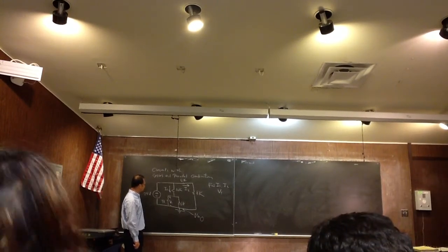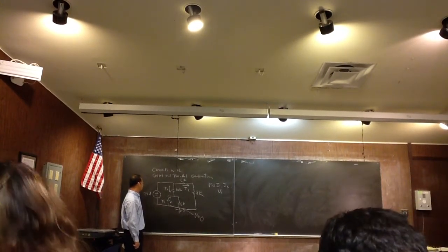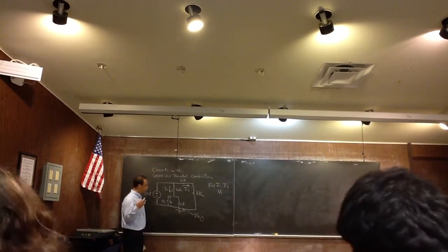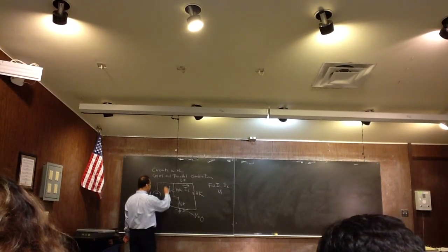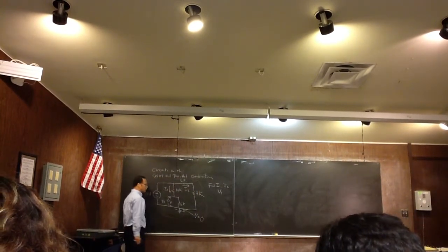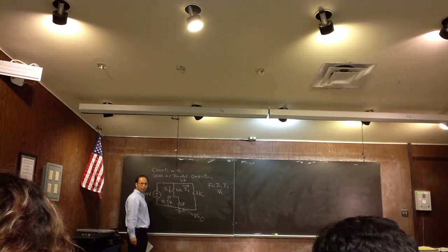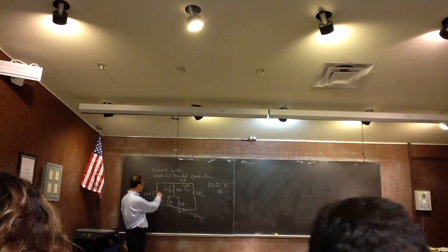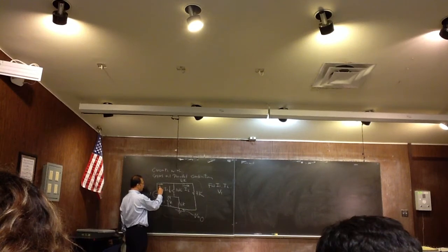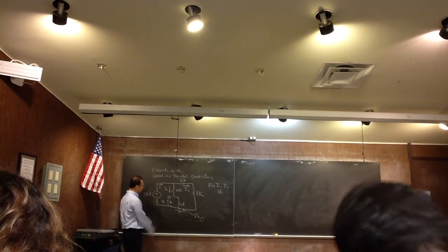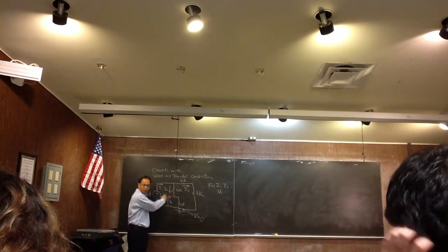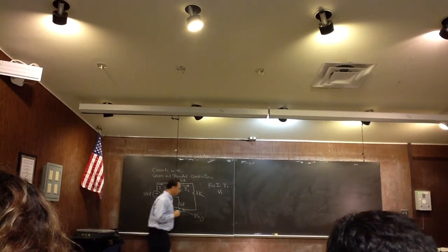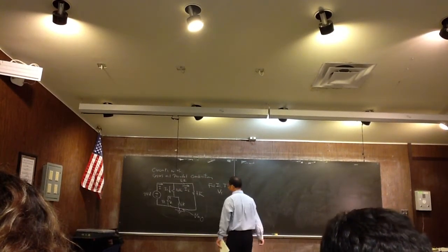Well, how do you solve this problem? There are many different ways. One way is the following. You can try to make a single equivalent circuit, a single equivalent resistance for that box, and then you can find the current. So there's a current, called I. Once you find the current, then you can use the current divider rule to find the currents I1 and I2. So let's do that. And then I will use a second approach later.